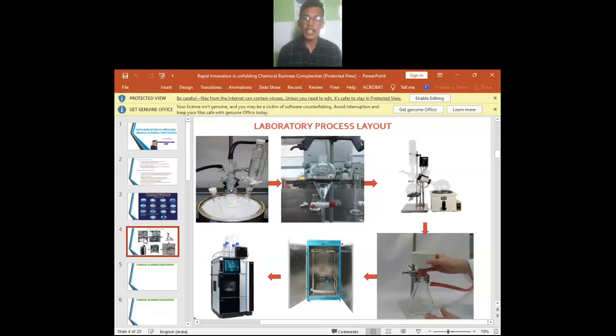The reaction mixture is then adjusted to a pH of desired product, and there is where the two layers form. First layer is aqueous layer, which contains the raw material, that is water soluble substances, and second layer is organic layer, which contains product, that is solvent based substances.